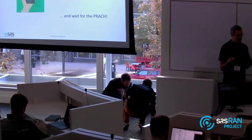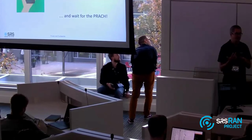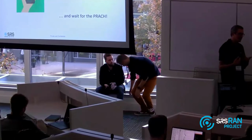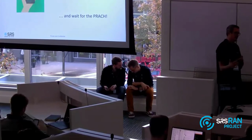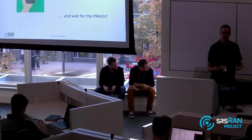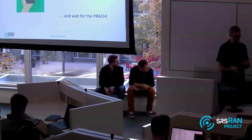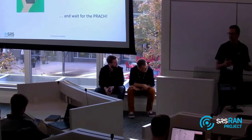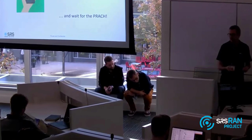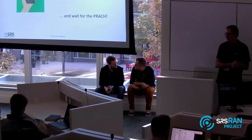Why? Because if you first turn off the gNB and the UE loses the signal, it will try to resynchronize again, and it might blacklist that channel because it might say, okay, this signal suddenly disappeared. I have been looking here for 1 minute. I don't see a signal. Next time I want to look here, I will look somewhere else. So it's always better that you make the UE think that the signal is always there. So next time when you turn off airplane mode, the first channel that it will go to look at will be this one, and it will attach very quickly.